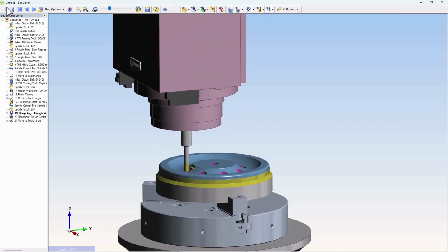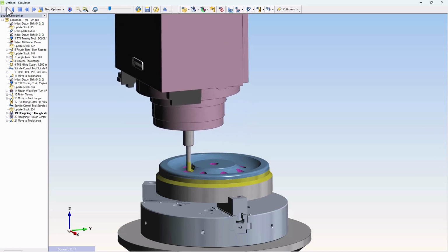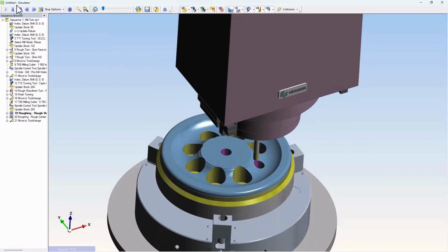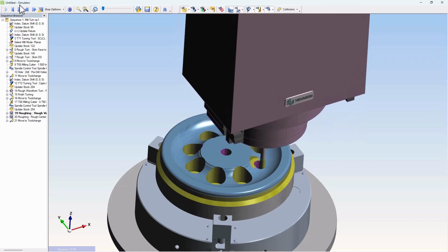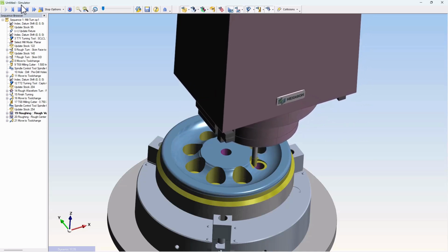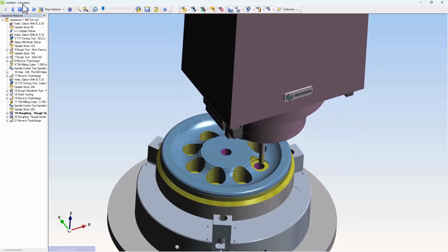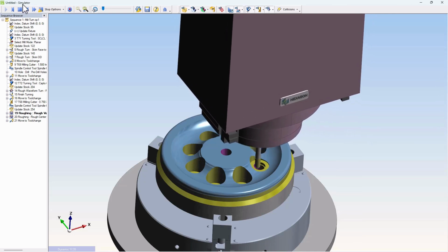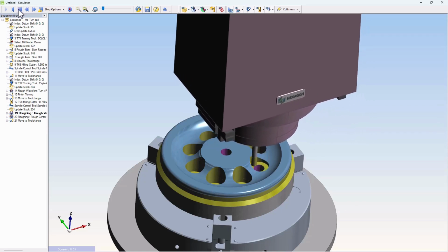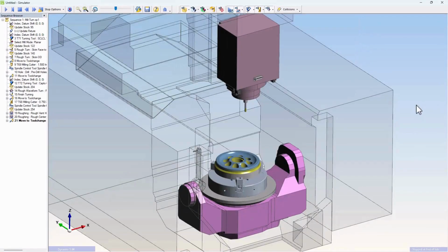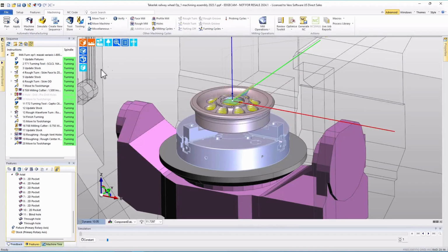tool. Now the milling tool is coming in to remove the access or weight reduction holes, and we see it uses EDGECAM's high-speed waveform roughing, which is stock aware and also aware of the entry hole, and that is used during the milling of those opened up areas. After that tool is done in the final outboard hole, it's going to move to the inboard hub, and we'll just mill most of the material out of that area rather than bringing in a boring bar, kind of dealer's choice. So we see the end of the current tool path in the part. We're going to go make some improvements to it.